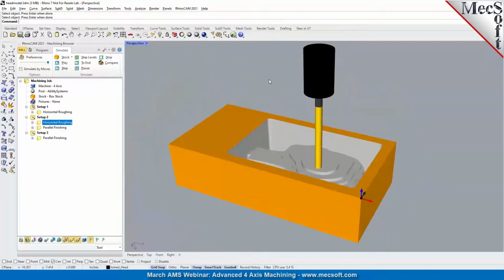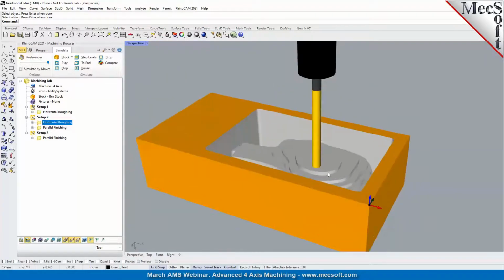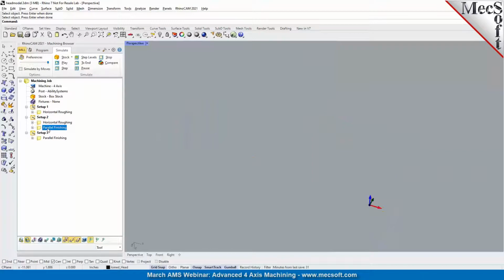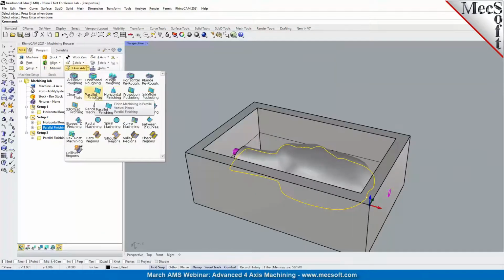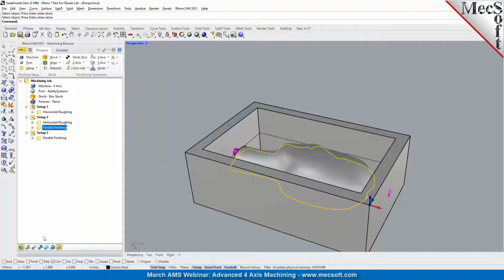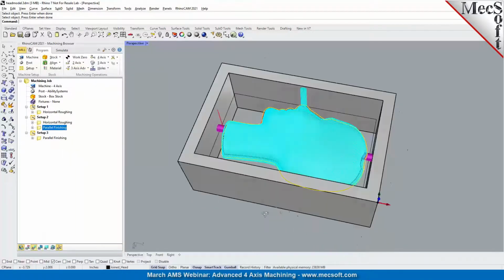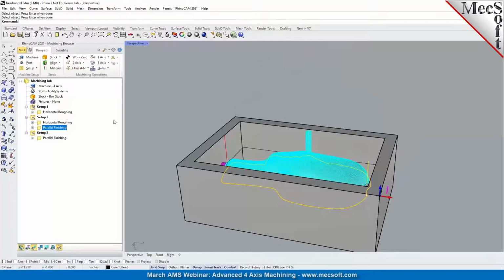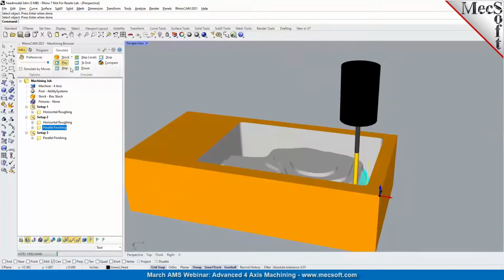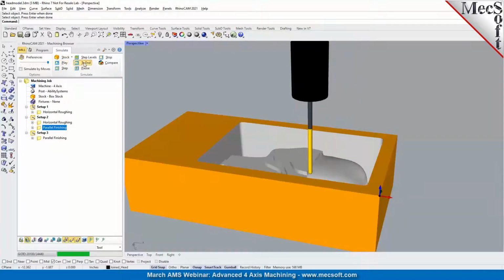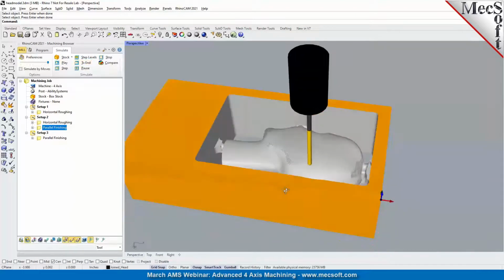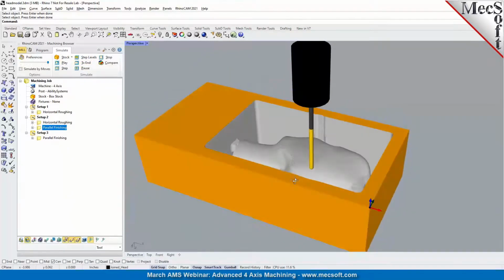Now, once the roughing is completed, we could go into a pre-finishing and a finishing operation. So we will program a parallel finishing operation in here from the 3-axis methods, parallel finishing. And I'm just going to use one of the operations in here, a 3-axis parallel finishing. And let's go ahead and run a simulation in here. So it's also known as index machining, could be 3+1 machining, where you can do a combination of 2 and 3-axis operations in conjunction with the rotate table setups.